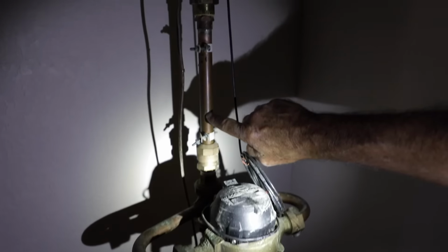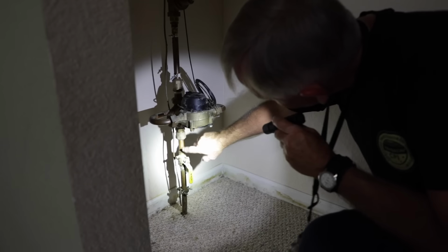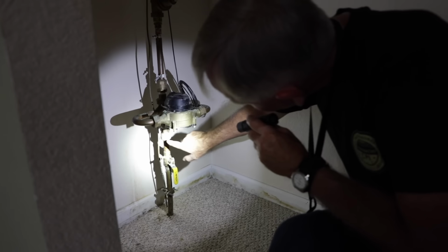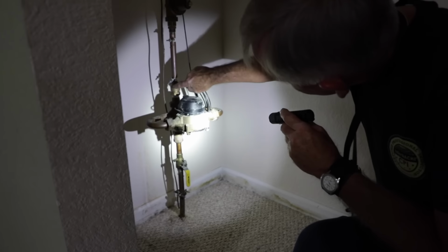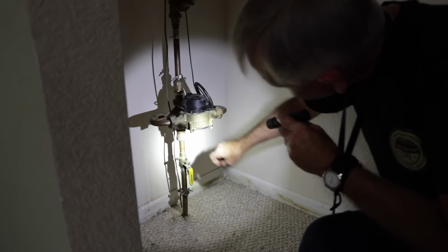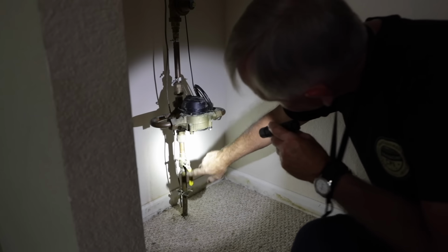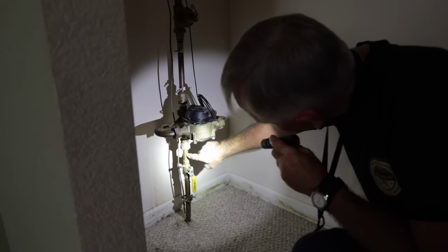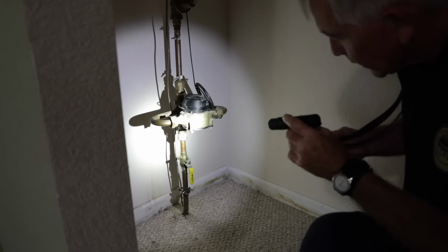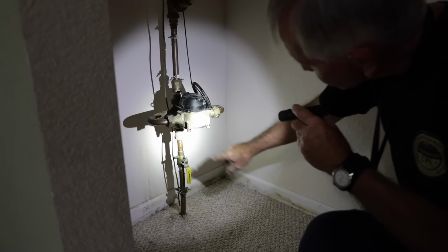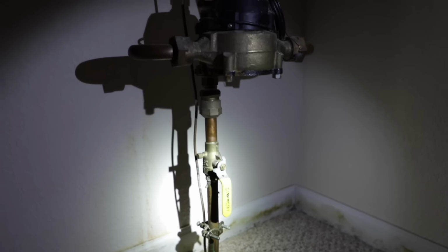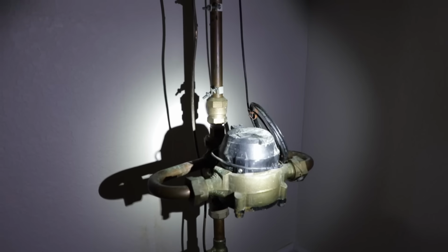The importance of this bonding jumper is that if the meter is ever removed for maintenance, or if any of these internal gaskets or seals on these fittings are non-conductive, then we wouldn't have the continuity through the water line like we want with our ground. So I'm just going to take a photo of that real quick. I'll mention that in my report. Everything else looks pretty good. That will conclude our grounding and bonding for this portion of the electrical inspection.